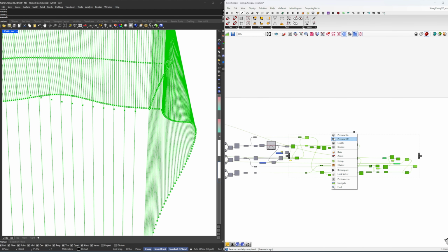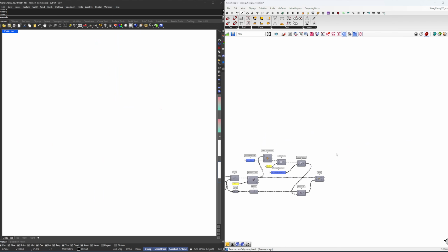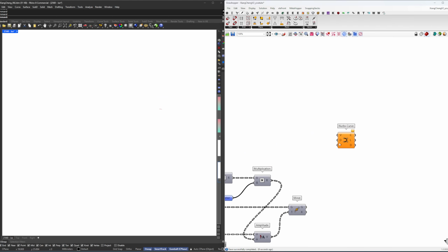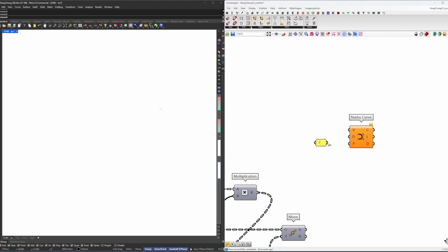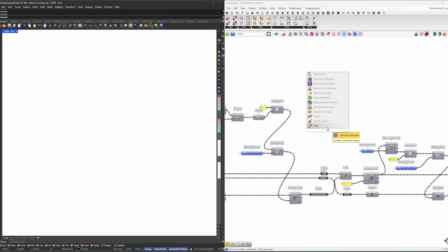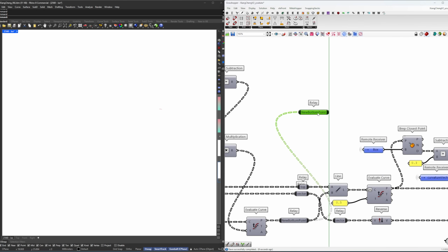What we're now going to do is we're going to recreate the facade curve. But now we're going to use a NURBS curve and put the degree to 2. It's automatically at 3, but we put it to 2. We need our new bottom curve, where is our new bottom point.